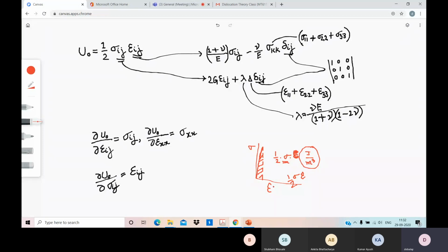But now actually you know sigma is not a single sigma. The sigma that we express in a tension test is basically your principal applied stress, sigma Roman 1. And the strain that we measure is basically the epsilon Roman 1, the principal strain. The cross-sectional plane is basically your principal plane on which maximum principal stress sigma Roman 1 applies. On the other two principal planes, there is no stress, sigma Roman 2 and Roman 3 equal to 0.